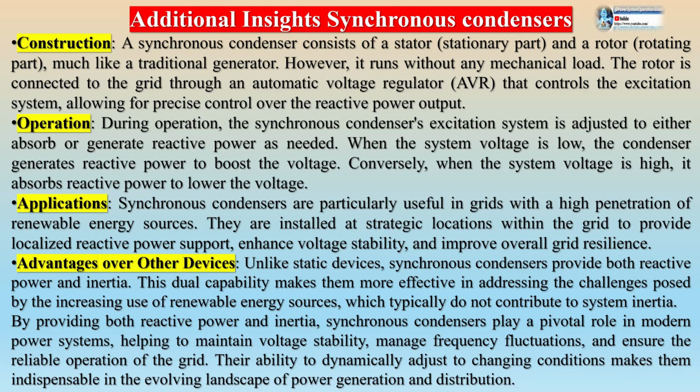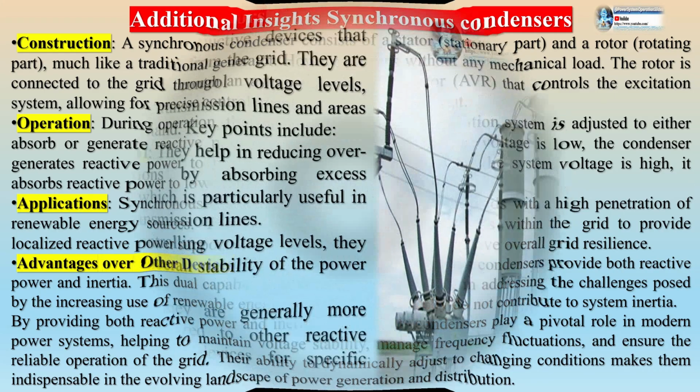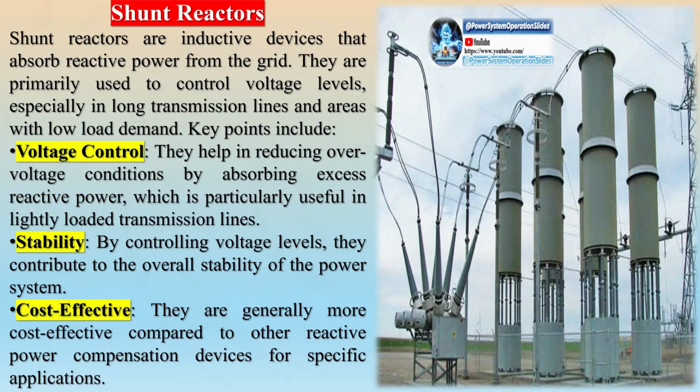Synchronous condensers are devices that function similarly to synchronous motors but operate without a mechanical load. Their primary purpose is to manage reactive power (VARs) within the electrical grid, which is crucial for voltage control and stabilization. Reactive power support: synchronous condensers can both generate and absorb reactive power. Reactive power is needed to maintain voltage levels within the grid, ensuring that the voltage stays within the desired range. This capability helps to stabilize the voltage, which is essential for the smooth operation of electrical equipment and the overall reliability of the power system.